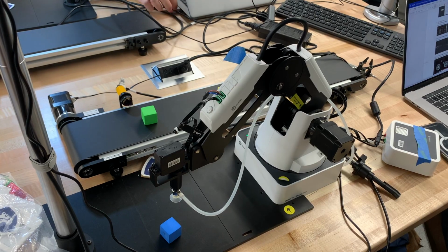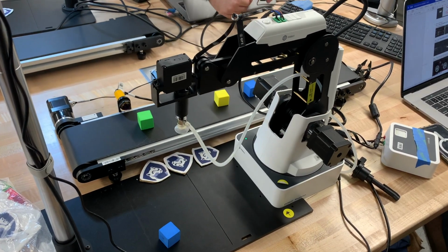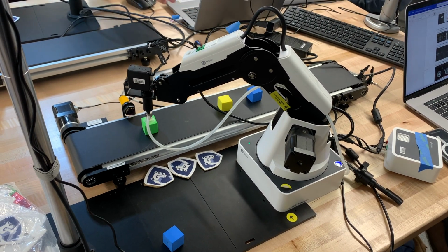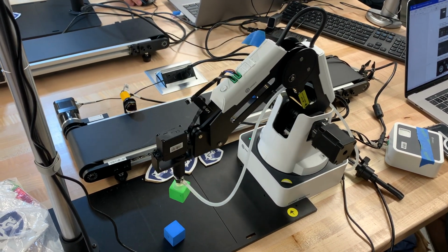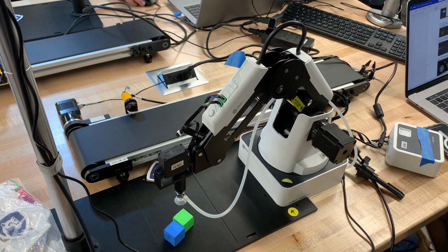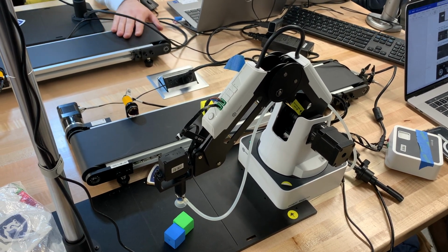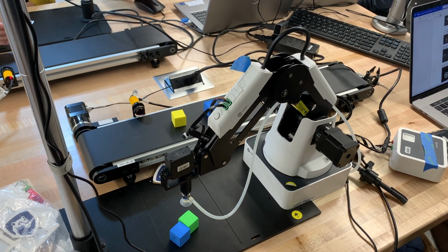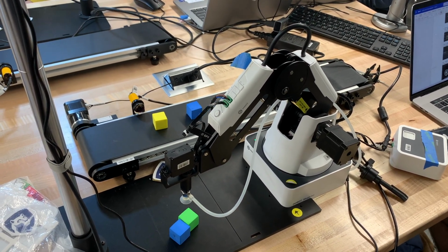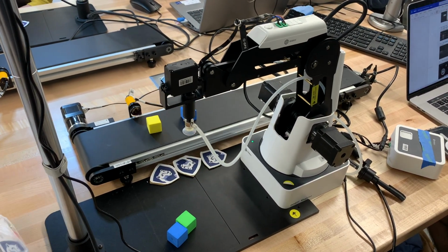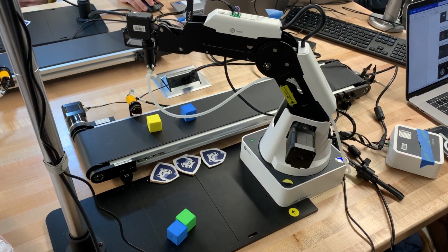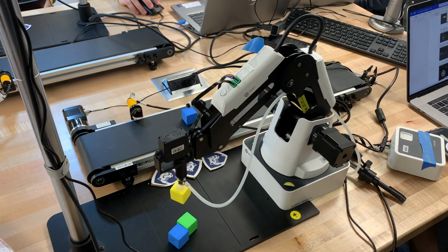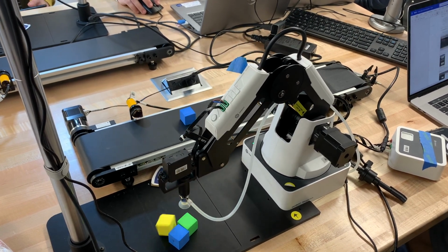For the software portion, we also learned a couple of new commands such as using branches. This allowed the flow to be separated into multiple subflows. This command was useful when the robot was waiting for input from the IR sensor, switching to the other flow when the IR was triggered. This allowed us to program the robot to pick up a colored block from the conveyor belt every time it reached the IR sensor and place it somewhere else.